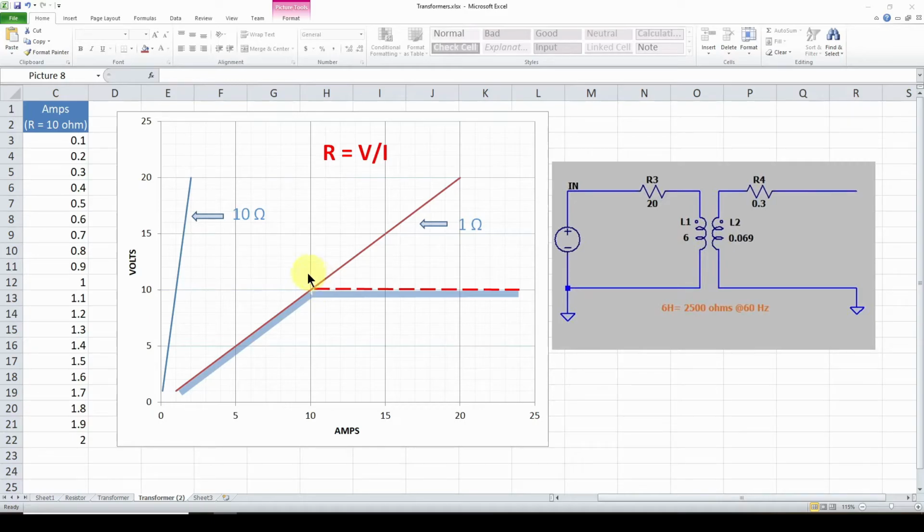However, above a certain amount of voltage applied to this transformer, suddenly the impedance, the inductive reactance of that transformer, would drop quickly. So in our case, we measured with 120 volts across this transformer about 47 or 57 milliamps, all right?